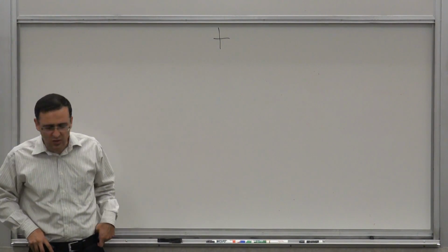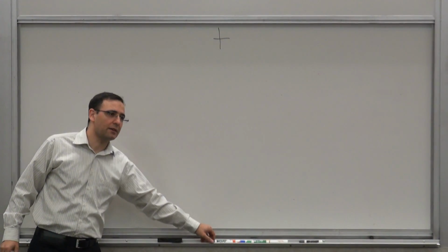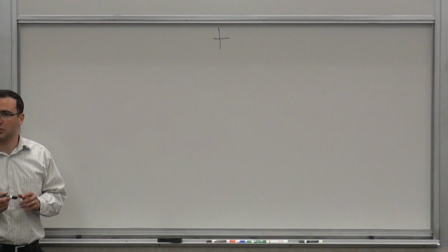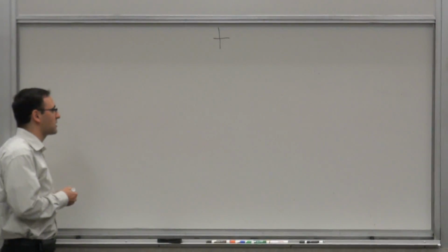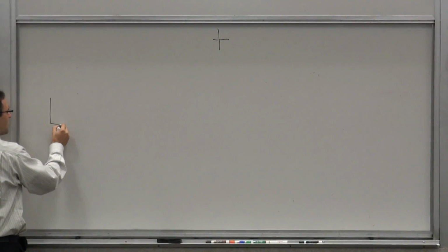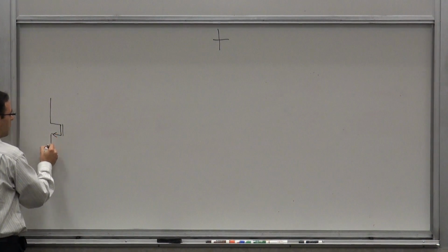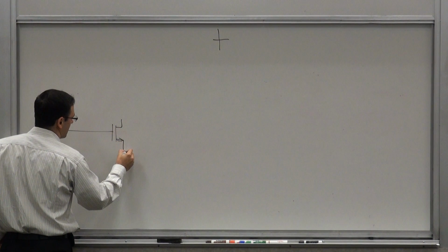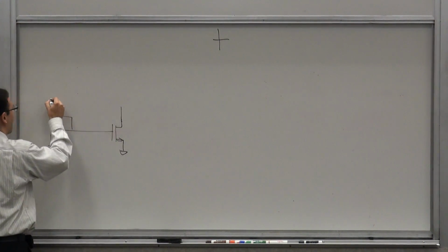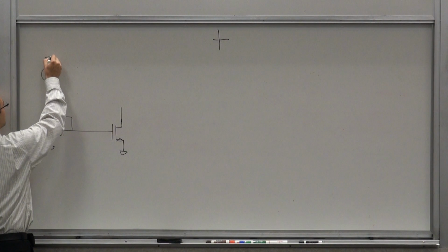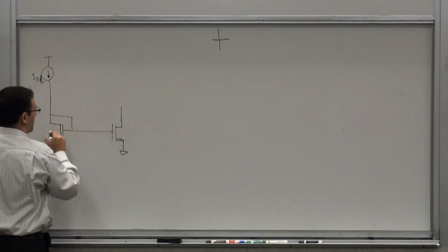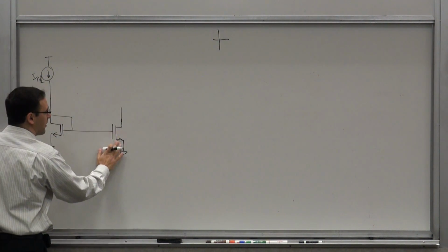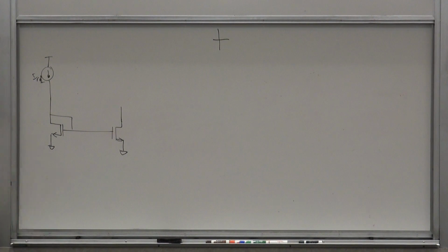Anyway, so one of the things that we did in the integrated setup was these current sources. So we said, well, how do we make current sources? We started with current sources, and we said the basic building block of a lot of these things was the current mirror. You can have a MOSFET or bipolar current mirror, and this is the simplest current mirror. So you have some reference current here that could be mirrored here. In general, it could actually be multiplied or divided by some ratio.